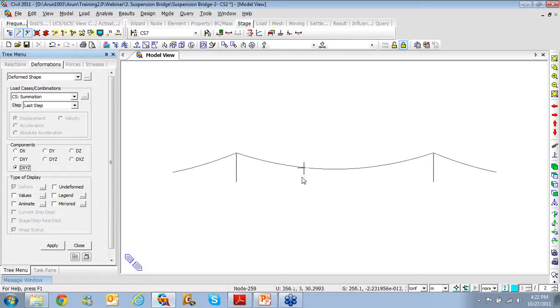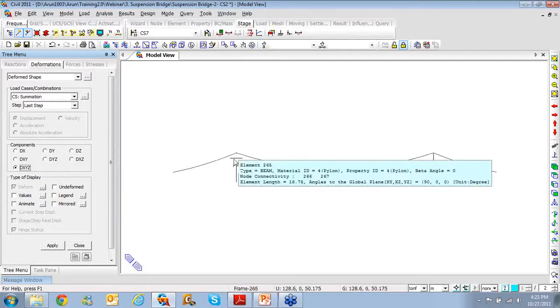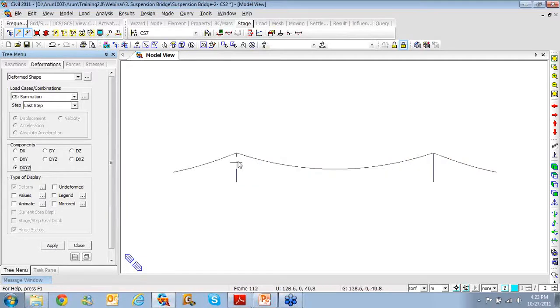Then as and when you start construction, you will see that the pylon will bend inside, and there will be cable slip occurring over the pylon. So in order to avoid this kind of pylon slip, and any unbalanced bending moment coming into the pylon, the construction practice is to apply some wires and pull the pylon back while it is in the initial stages of construction.